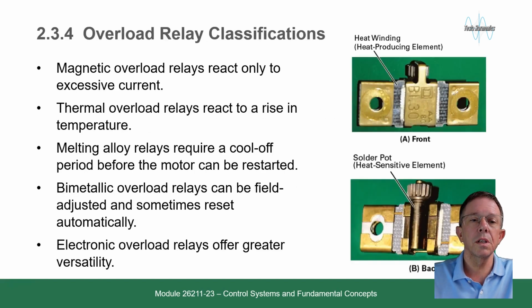Magnetic overload relays react only to excessive current. Thermal overload relays react to a rise in temperature. Melting alloy relays require a cool-off period before the motor can be restarted. Bimetallic overload relays can be field adjusted and sometimes reset automatically. Electronic overload relays offer greater versatility.